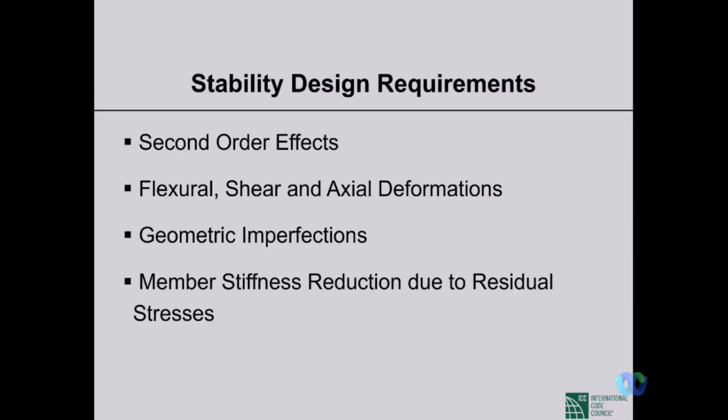So you see, as I have already mentioned, for steel design, buckling is a major problem, and we have to always be careful about that. Buckling analysis is called stability analysis. When something buckles, we call it instability. So stability design is very important, particularly for lateral load. Gravity loads will impose compression on columns, but when there is lateral load, that causes some problem. We'll see that.